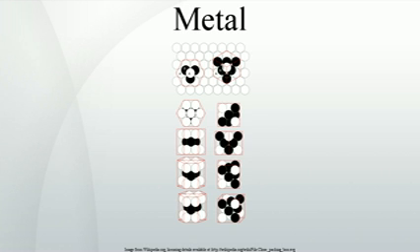Of all the metallic alloys in use today, the alloys of iron (steel, stainless steel, cast iron, tool steel, alloy steel) make up the largest proportion both by quantity and commercial value. Iron alloyed with various proportions of carbon gives low, mid and high carbon steels, with increasing carbon levels reducing ductility and toughness. The addition of silicon will produce cast irons, while the addition of chromium, nickel and molybdenum to carbon steels, more than 10%, results in stainless steels.